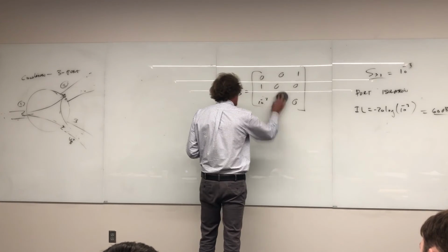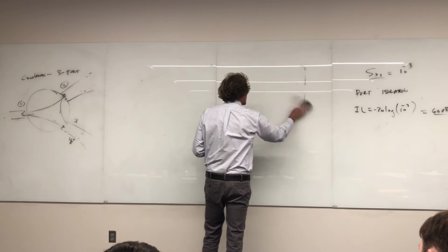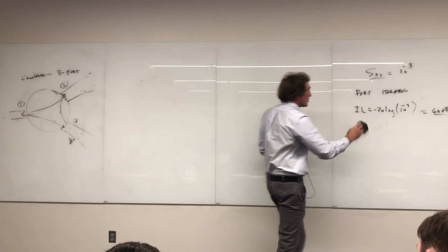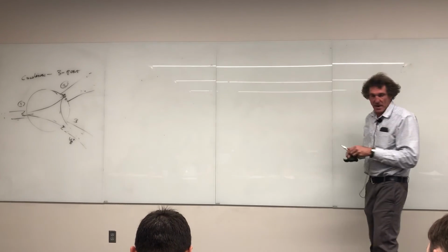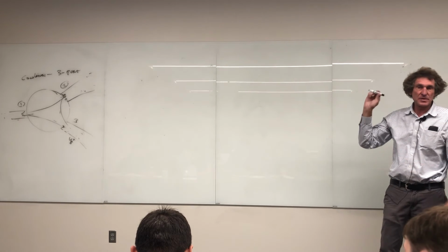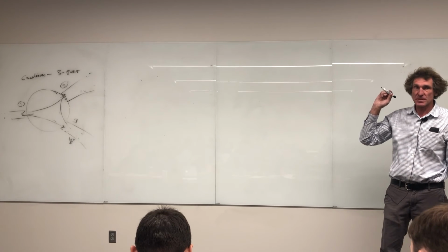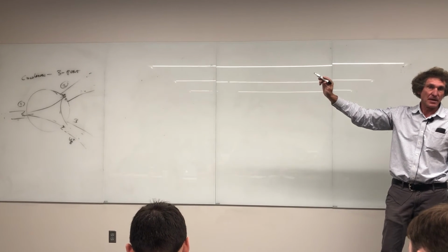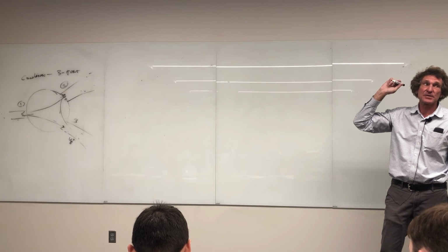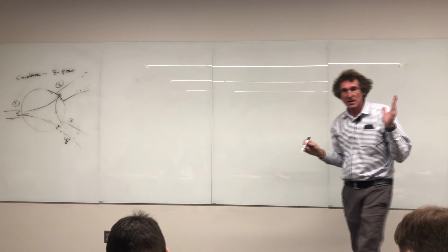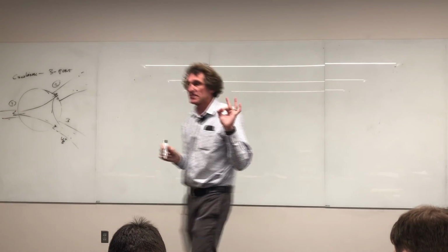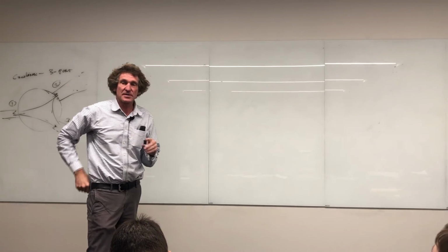Now, Dr. Wentworth probably could give you a lot more background on why it is so important to have this isolation port. But normally what happens is this. With microwave, what you want to do is you want the power to get to a device or an antenna. So you're going to have something like an S21. What comes out port 2 from port 1? You'd like that to be 1. 20 times the log of 1 is 0. You'd like 0 dB of attenuation or isolation there.